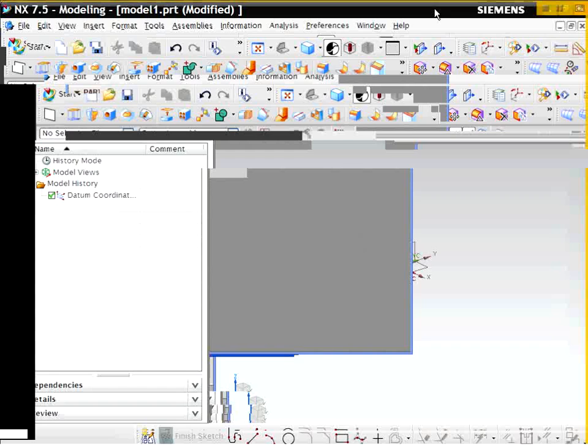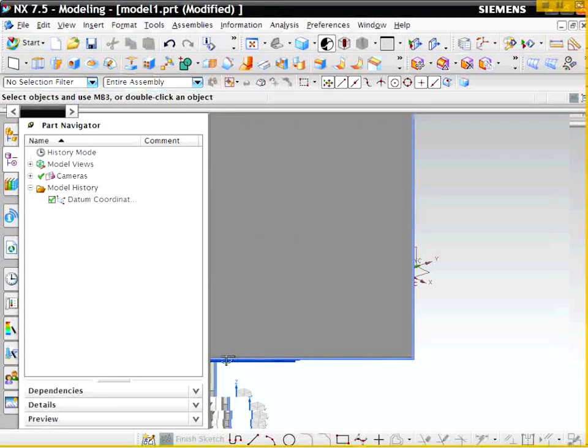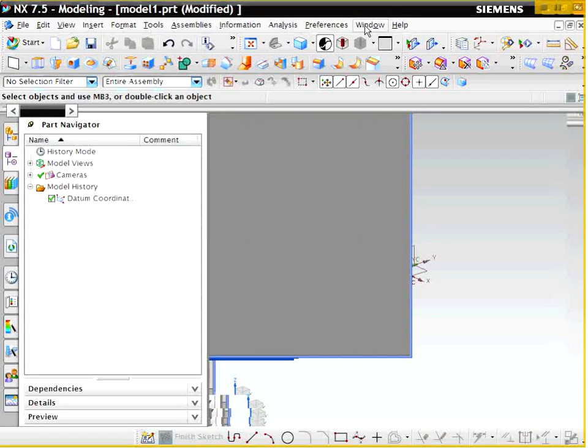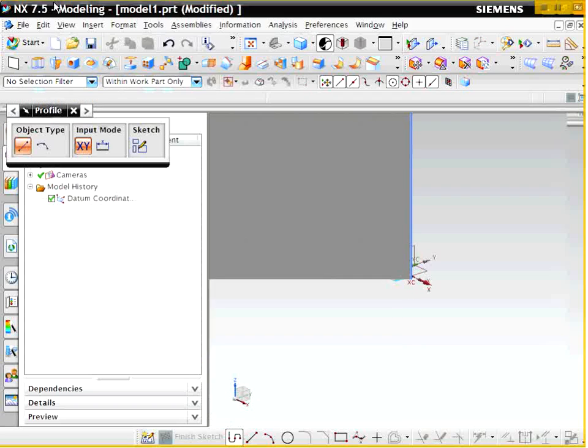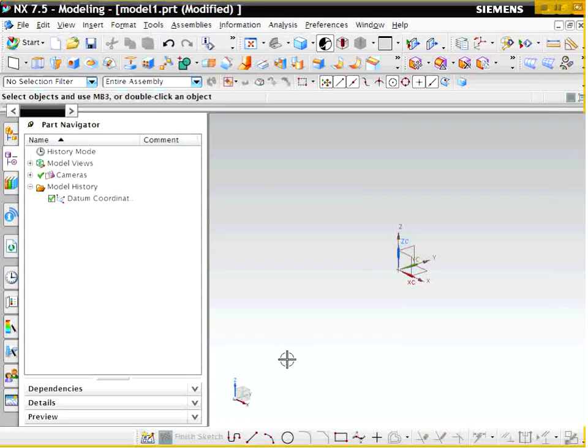Let me continue my third lecture in Chapter 6. This one should be relatively short. I'm just going to talk about revolved features. Revolved features just allow us to draw a two-dimensional sketch and then rotate it about an axis. By doing this, we can create a three-dimensional geometry that represents something. In this case, we're going to be drawing a nozzle geometry.